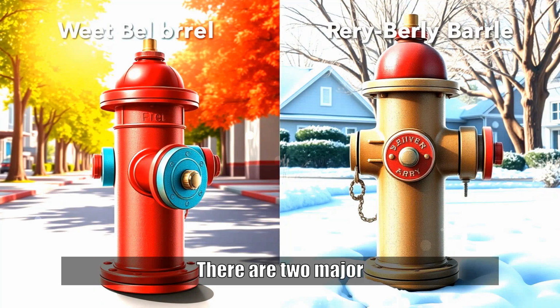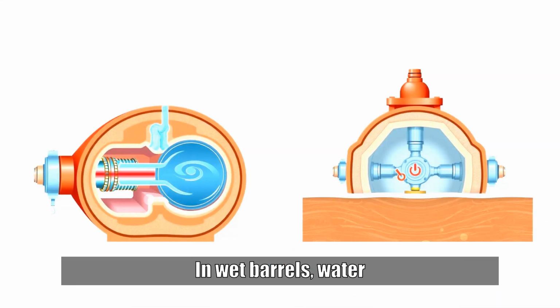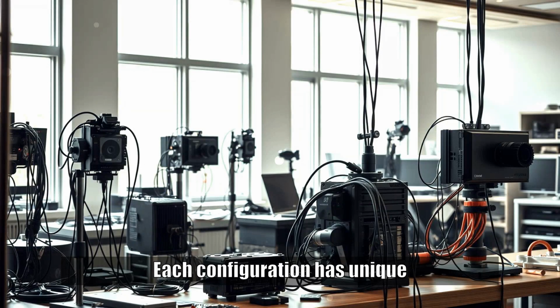There are two major hydrant configurations: wet barrel hydrants, common in warm climates, and dry barrel hydrants, suitable for freezing environments. In wet barrels, water remains pressurized in the hydrant at all times, while in dry barrels, the valve is located below the frost line, and the hydrant only fills when activated. Each configuration has unique installation requirements.